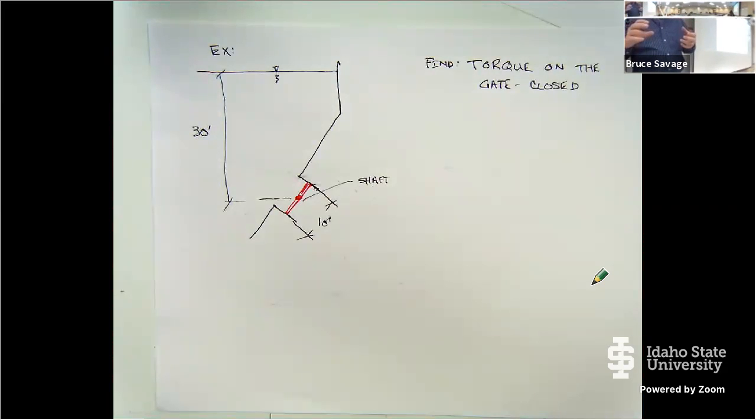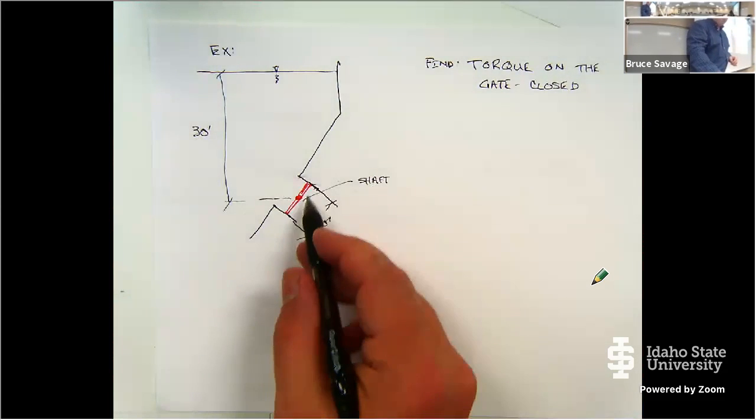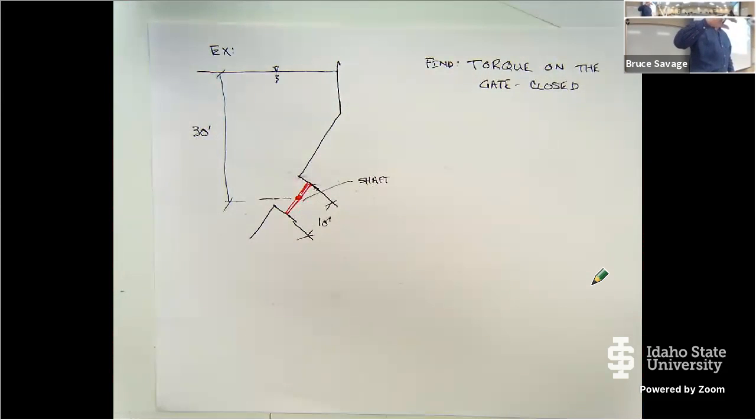The first question, let's ask ourselves, why would it open? If I have this butterfly valve in there and I have no torque on that shaft, would it open? And if it does open, why would it open? What's the principle that would force it open? There's more pressure on the bottom half of the valve than the top because it's deeper in the water. Good, yes. Remember, pressure increases as you go deep. So higher pressure on the bottom and lower on the top, so that thing's just going to rotate, okay?